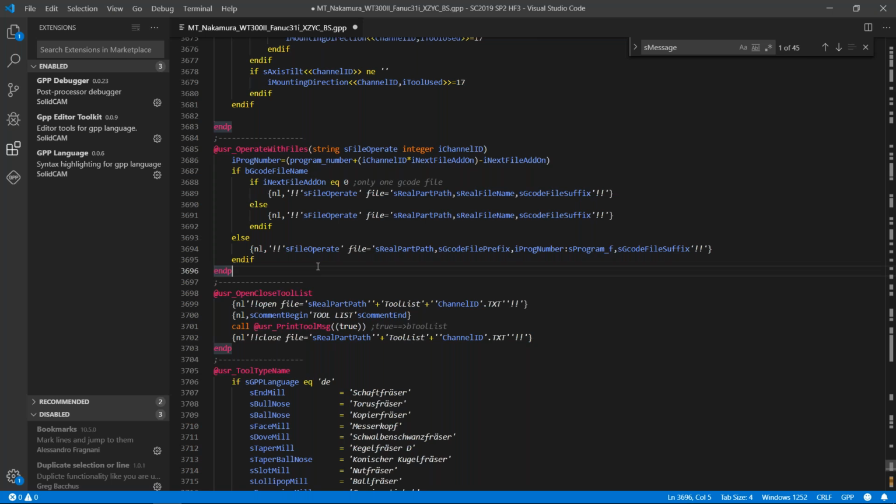Yes, but actually, the debugger is like a Matrix movie. Okay, you can stop basically the time of your G-code generation and navigate and analyze the data at any moment. So what that means is, once I hit the G-code generation button, I can at any time stop the G-code generation and I can analyze or change the data inside of it. Okay, now maybe this sounds a little bit creepy, especially if you're here for debugging for the first time, but the debug mode is something very common for all programmers and developers.